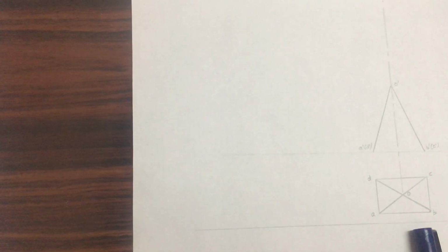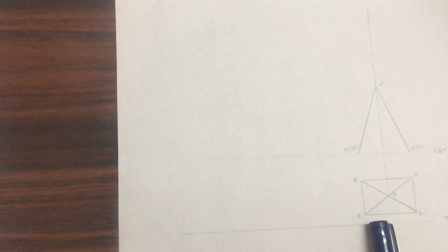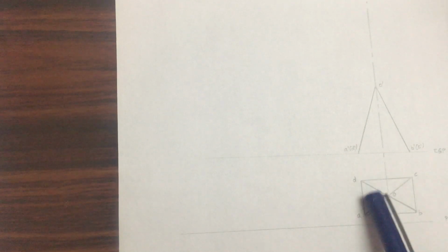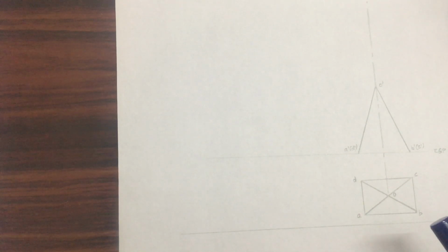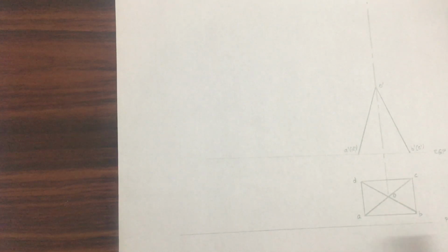So, 30 by 20 is the dimension, and 5 mm behind the picture plane. You have taken 5 mm from here, and the edge parallel to the picture plane is 30 mm. Then you have taken 20 mm over here, and then you have terminated the rectangle. As it is a pyramid, the diagonals are visible, so you can draw the diagonals also, which is named as ABCD. The center point is named as O.